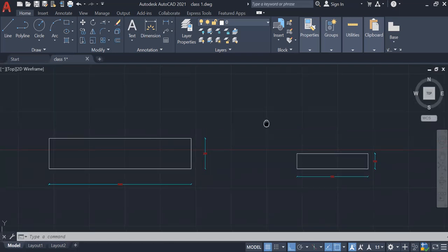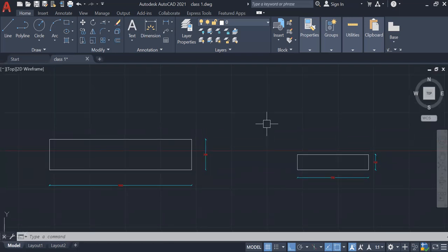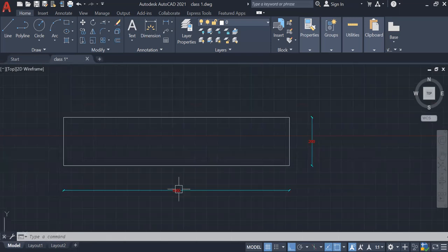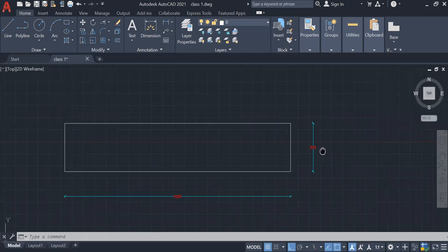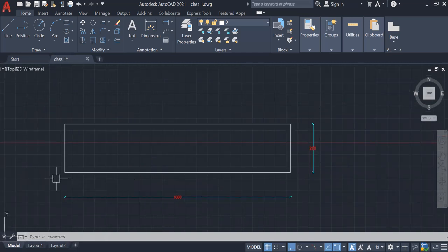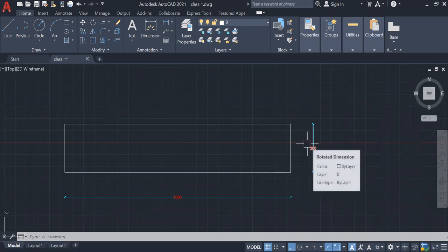Okay. So while doing the drawings, I will tell you how to use the scale factor, because sometimes, for example, here you can see this one. This is 1,000 and this is 200. If you take the print and measure this one, it will come 1,000 centimeter and 200 centimeter. Okay, but on the page, if it comes the same as whatever is there, then it becomes 1:100. Again, if you change the scales, then again 1:50, 1:200, 1:100, 1:10, 1:5, again 1:500, 1:400, like that. Also we can use different scales for different drawings.